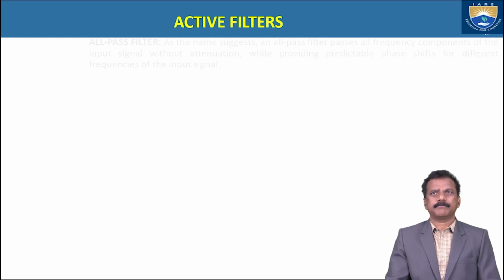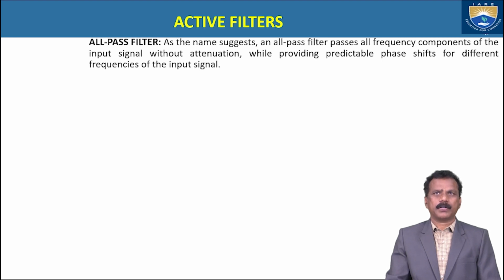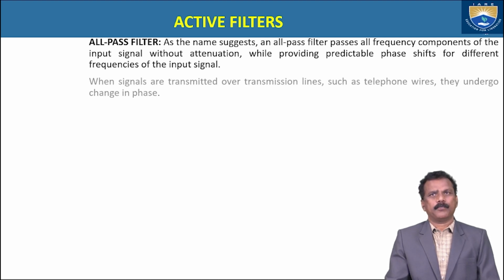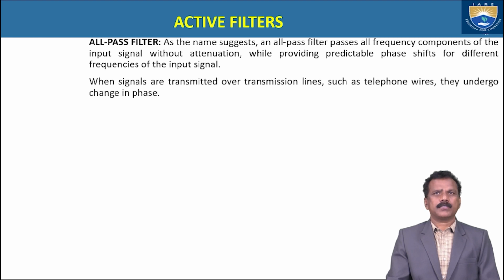Okay, now coming to the all pass filter. As the name suggests, an all pass filter passes all frequency components of the input signal without any attenuation, while providing a predictable phase shift at different frequencies of the input signal. That's why it is the all pass filter.